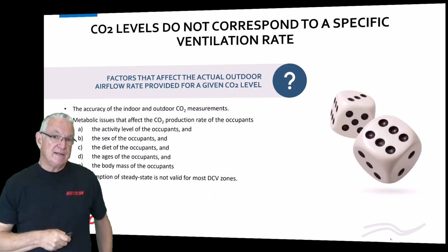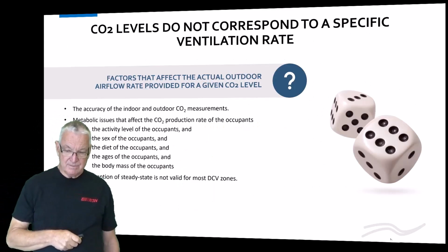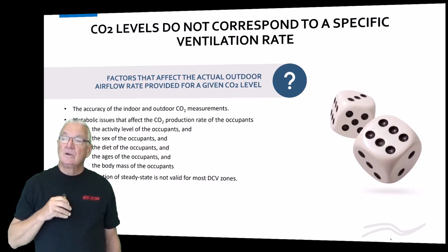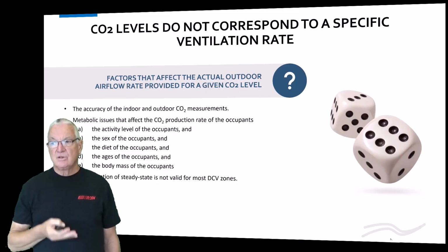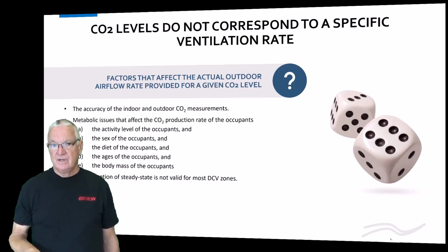So the problem is, there's a lot of problems actually, but once you realize that you're measuring CO2 as a proxy for outdoor air CFM per person, the next question you should have is how much uncertainty there is in the amount of outdoor air that I'm bringing in.